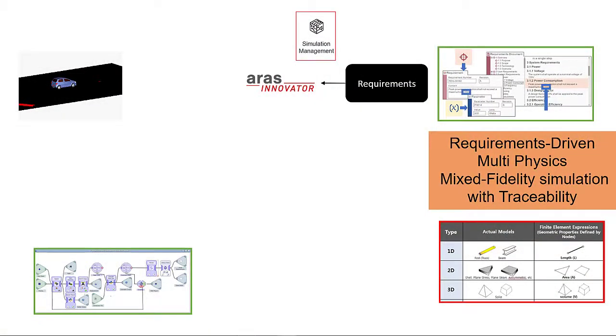The requirement gives us concrete data on what we should test. For example, if you test the brake system, then you have the conditions: 100 km/h, a rainy road, and we have to stop the car inside 36 meters. That is the requirement with 3 conditions.